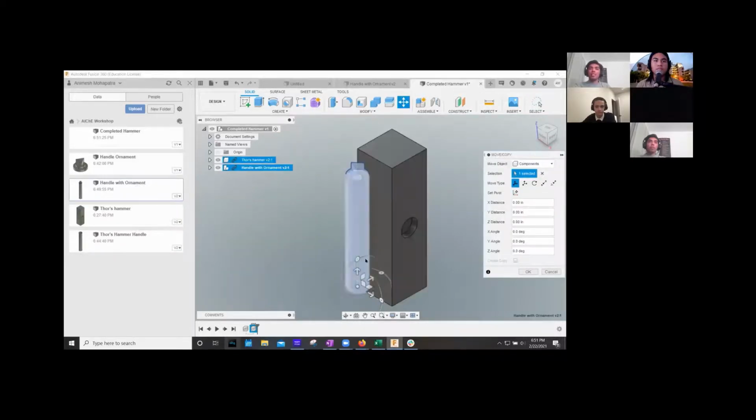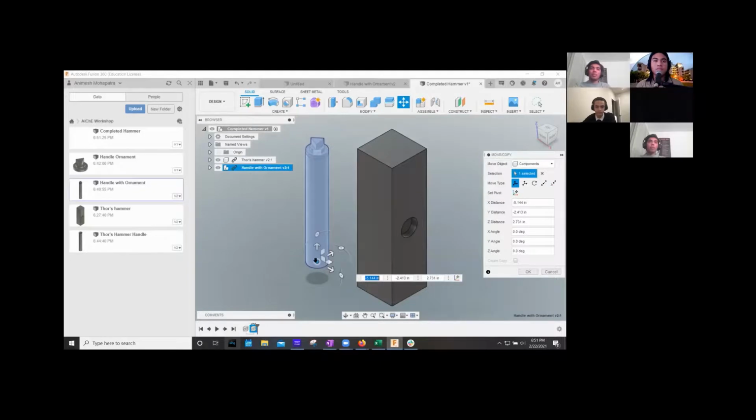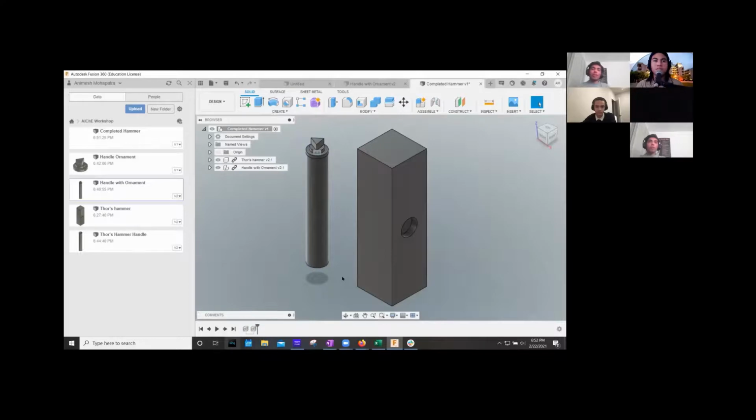Oh, they're kind of inside each other, so I'm just going to move this over here for my convenience. Then I'm going to press enter. So now everything is nicely in my file. All right, now I want to put them together. My general rule is that unless I have some definite source which absolutely cannot move, I use the smaller component to be component 1 during assembly.